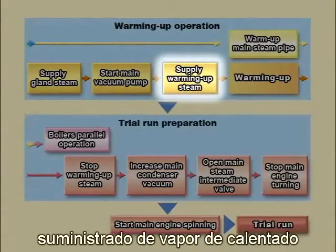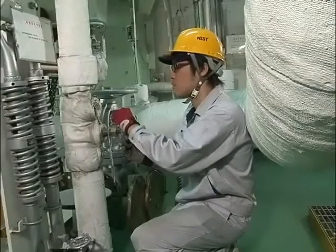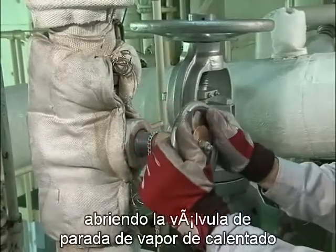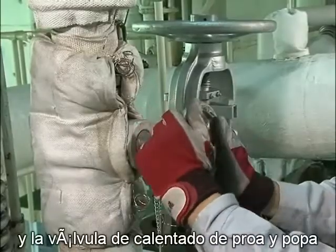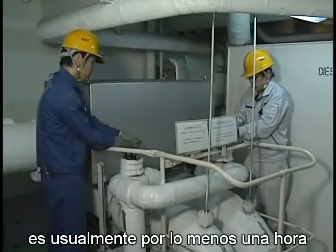Supply warming up steam. Supply warming up steam by opening the warming up steam stop valve and ahead and astern warming up valves. Time required for warming up is usually at least 1 hour.